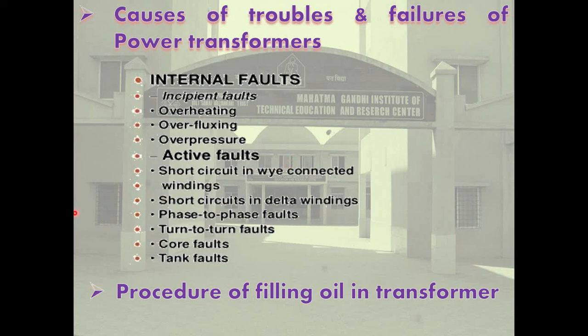Now, moisture in oil. Okay, moisture enters the oil while filling, breather saturated, defective scales, seals, etc. Oil should be filtered. Silica gel should be replaced. Gaskets should be replaced. Transformer should be dried out.